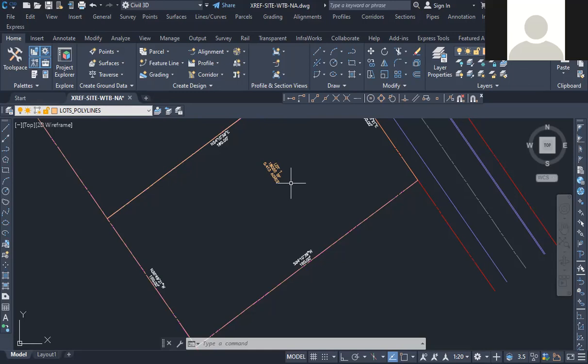So most of the time, what we do is if it's a square lot, we're all big engineers. We can take one dimension and multiply it by another dimension. So you can't hide the rounding because it's going to have a rounding up or down, agreed? You can't really do that in the lots, especially the lots that are square. So normally where you take out your rounding errors is in the road right of ways. Okay.